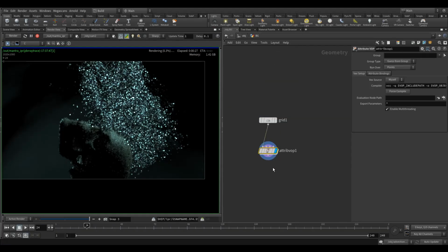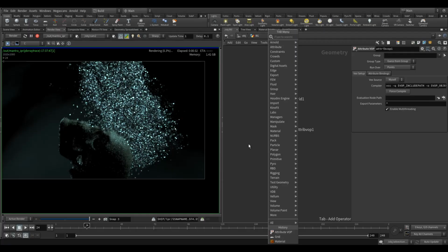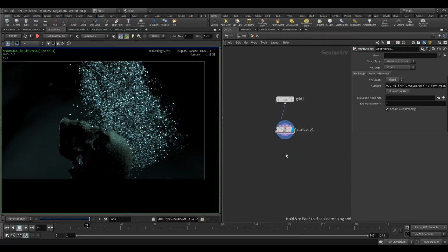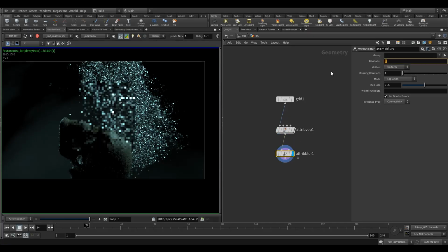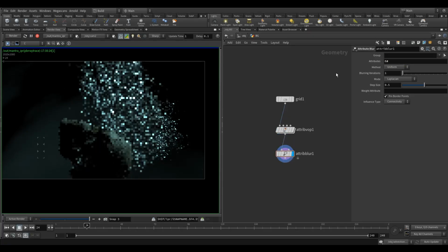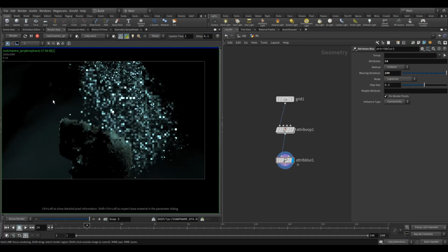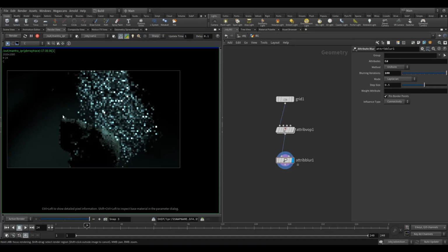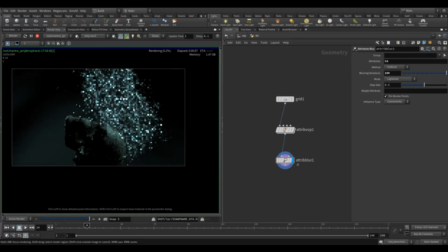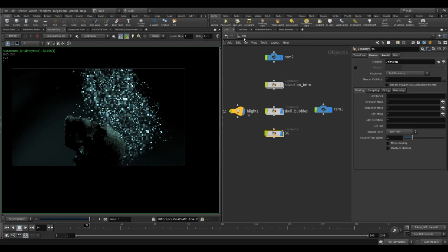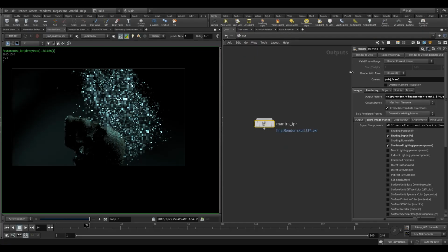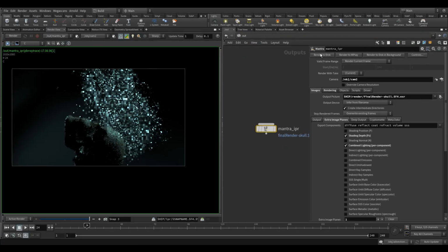I think what I'll do is blur that a bit. So if we come back into the background SOP level and go find an attribute blur, by default this is set up to blur the position. Yeah, we're going to blur the color, so Cd. We should see that change. Blur it a load more. There we go. So you see it's really just almost like a fog in the background. Great. Okay, so I'm going to stop that and then render that out again. Just leave this, render it over. That's fine. It doesn't matter. So render to disk.